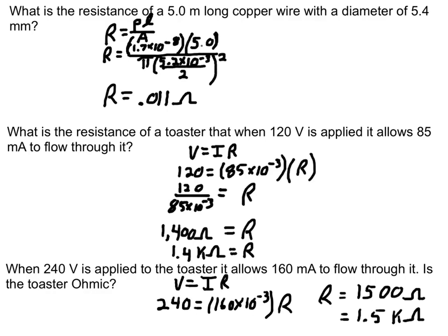And you can see here that as I increased my voltage, or my electrical potential difference, as I pushed harder, I actually got less current. I actually doubled the voltage and did not get double the current, meaning that the resistance went up. For something to be ohmic, the resistance must stay constant here. So this is a non-ohmic device. As you push harder, you get less return.